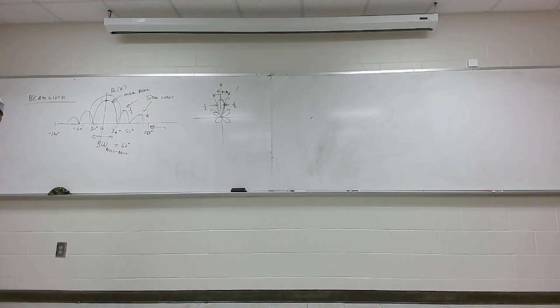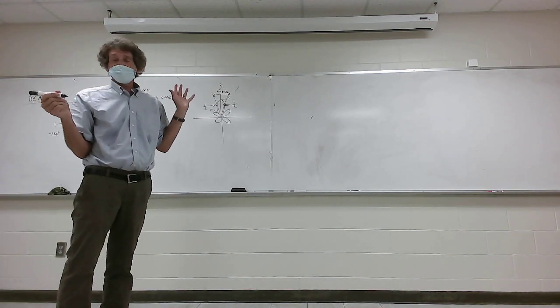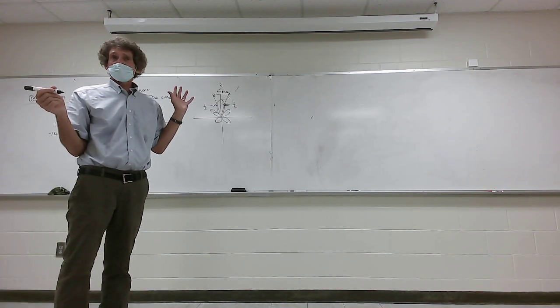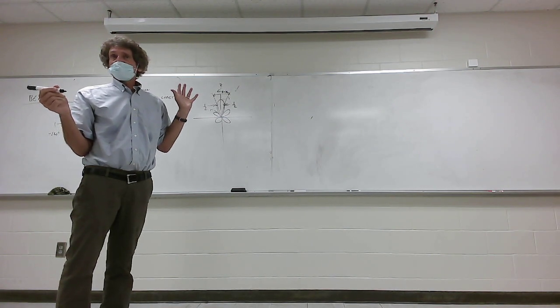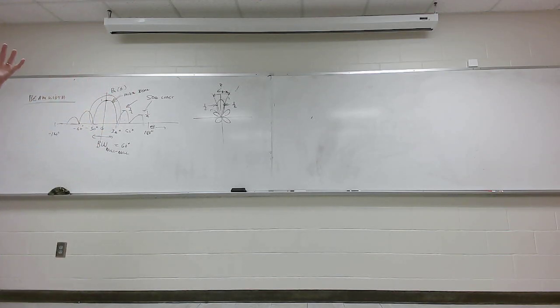For an antenna like a half wave dipole, that thing is massive. It's about 90 degrees, which is horrible for any kind of focusing. For any kind of target acquisition radar, like used on an aircraft carrier or out at Atlanta Airport, where they want to be able to single out an aircraft, find its range and its velocity, that's maybe 1 degree to 2 degrees. Sometimes sub-degrees, all right? Very narrow beam.